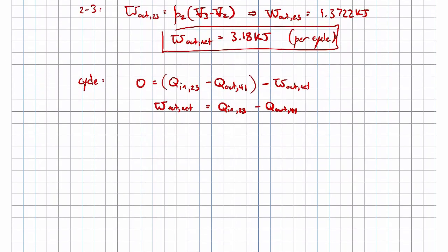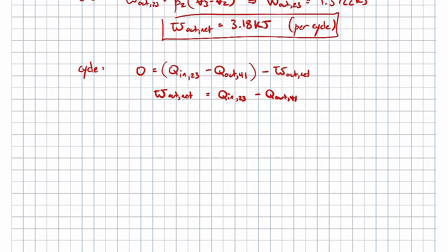So when we apply the first law there, on the left-hand side, it'll be the mass times U1 minus U4 equals minus Q out 4 to 1. And then again, there's no work because it's a constant volume process. So we can solve for Q out. When you work out those numbers, that comes out to be 2.6025 kilojoules.